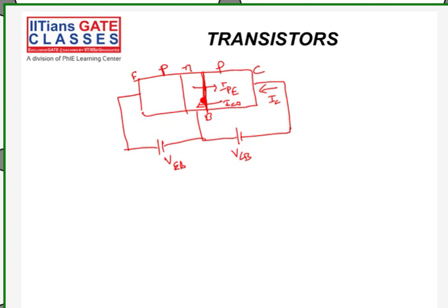So conventionally it is indicated from collector to base. This ICO will be flowing opposite to the reverse IC. So here ICO will be negative, because its flow is from collector to base. That is why I'll consider it in this direction. Second thing, ICO is in which region? It is in PNP. I'm talking about PNP. If I talk about NPN, it will be positive in NPN.